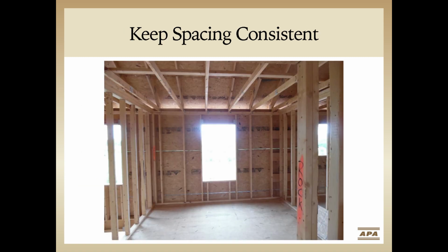So this photo was used earlier when we were talking about cripple studs not being ideally spaced. I now want to point out the light showing between the wood structural panels. Some may think this is an issue, when in actuality, this is a very good thing. These panels are spaced properly and will be able to expand as they acclimate. When we see panel buckling in the field, it almost always comes down to the panels being restrained, and that's often by lack of spacing. And when they're restrained, they're unable to expand as they acclimate.